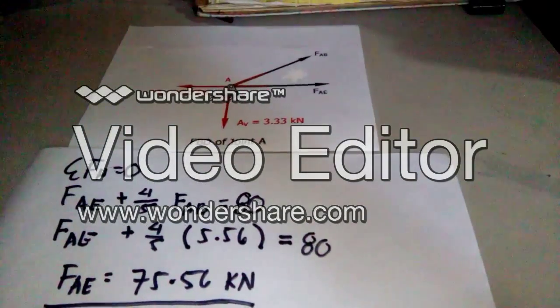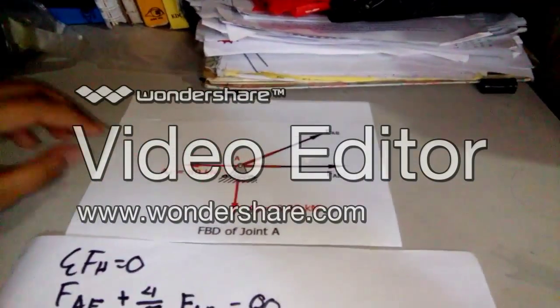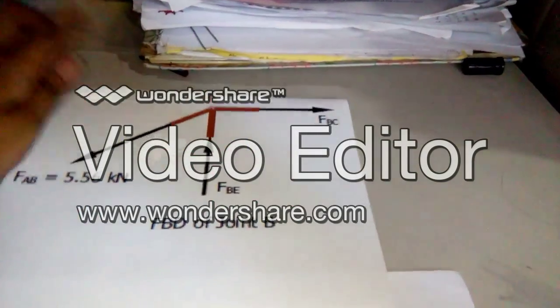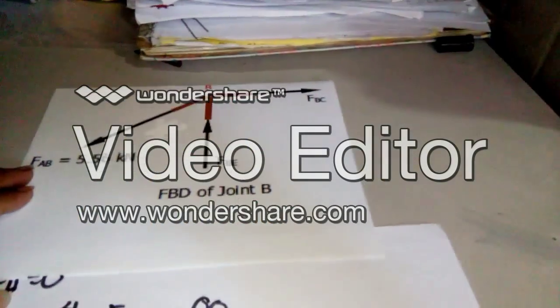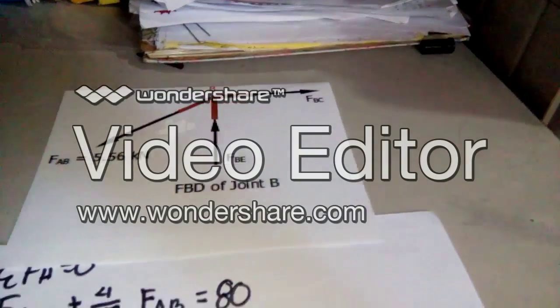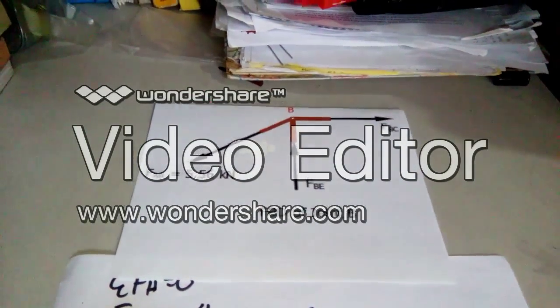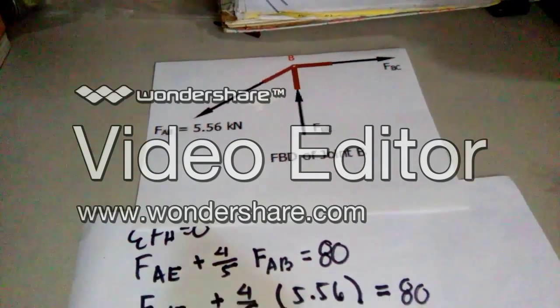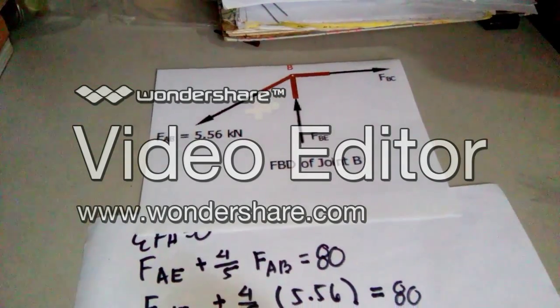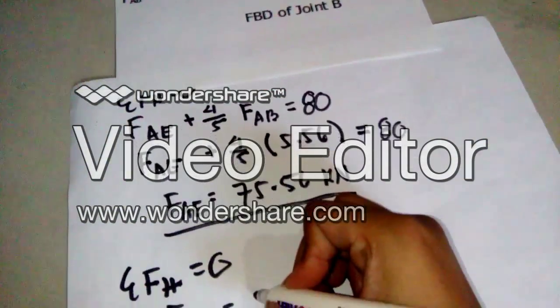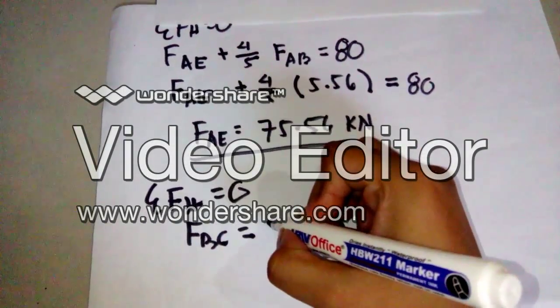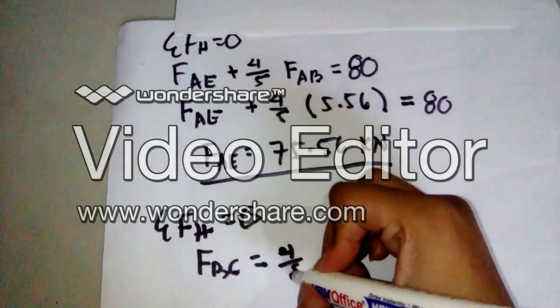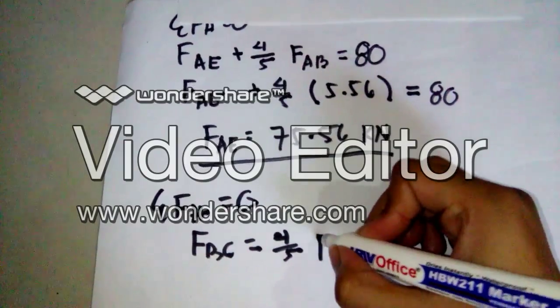So, moving on, we have the FBD for joint B. Using the summation of horizontal force is equal to 0, FBC is equal to 4/5 FAB.